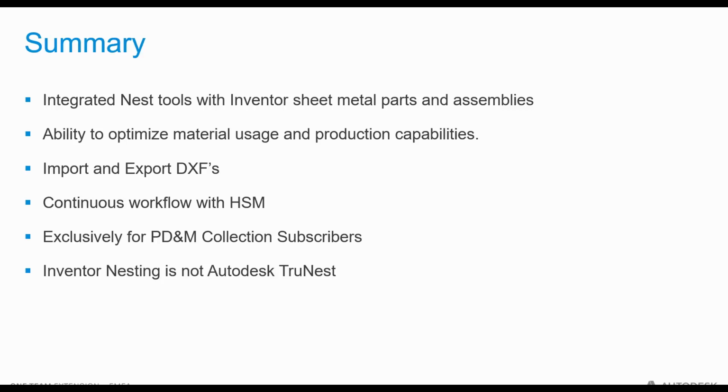So the idea of getting you to work in the Inventor environment, I suppose, is the added option of the pack and go assembly environment. So what it does for you is, the pack and go option is basically you can send out your assembly from start to finish, including your nesting files, to somebody else, and they would be able to view the assembly and the files and the nesting files on their own without any hassle.